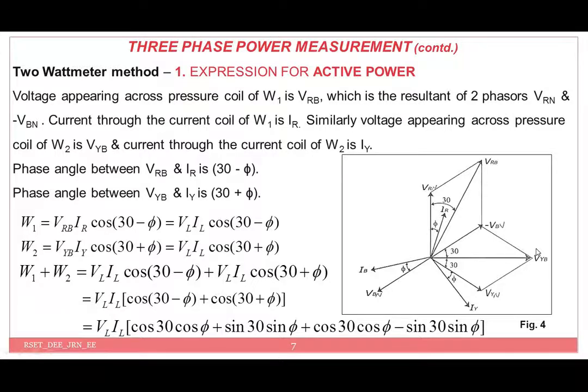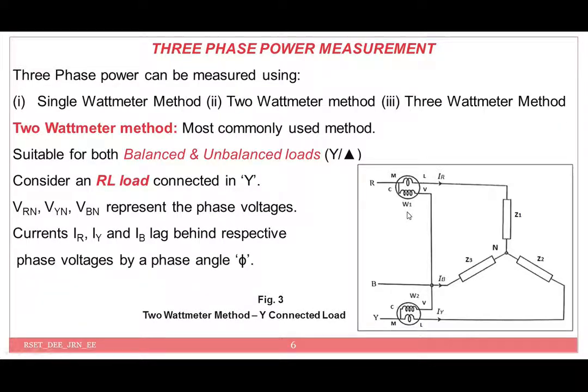Now you can see one thing over here. This is my wattmeter W1, which is included in my R phase and Y phase. It can even be connected on R phase and B phase, or it can be connected on Y phase and B phase.